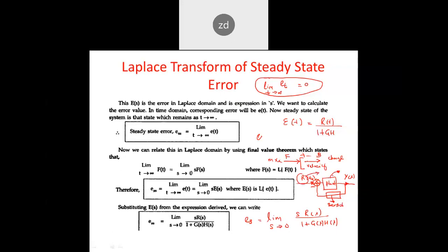In electrical and communication systems, it's quite easy by monitoring the voltage and other factors, but when it comes to electromechanical and magnetic systems, we definitely go for certain test signals. The elementary test signals we choose as input in control systems start with the unit step signal, which in the Laplace domain is 1 by s. If it's a unit ramp, it would be t, and in the Laplace domain it is 1 by s square. Similarly, the parabolic is 1 by s cube.